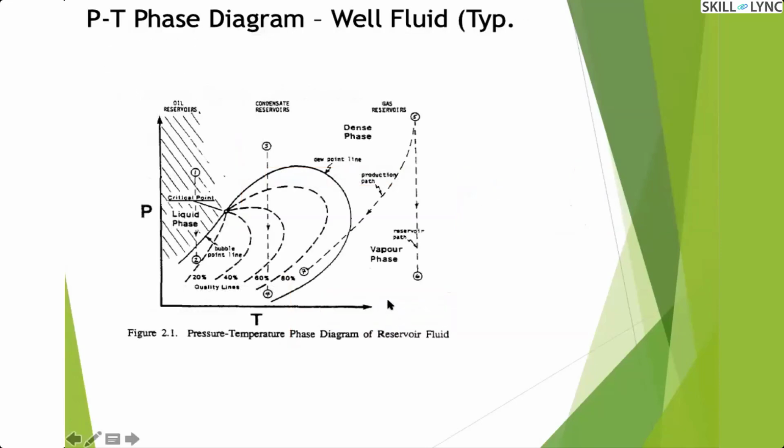Yeah, so now this is a typical phase diagram. This phase diagram is what I was explaining. This will be dependent upon your fluid package selection. Only based on this phase diagram. So here if you see, beyond this it will be in the liquid phase, when this is your pressure and temperature zone. When your temperature and pressure are lying in between these two lines, then it will exist in two phase conditions. And when it goes beyond this line, it exists in the vapor phase.